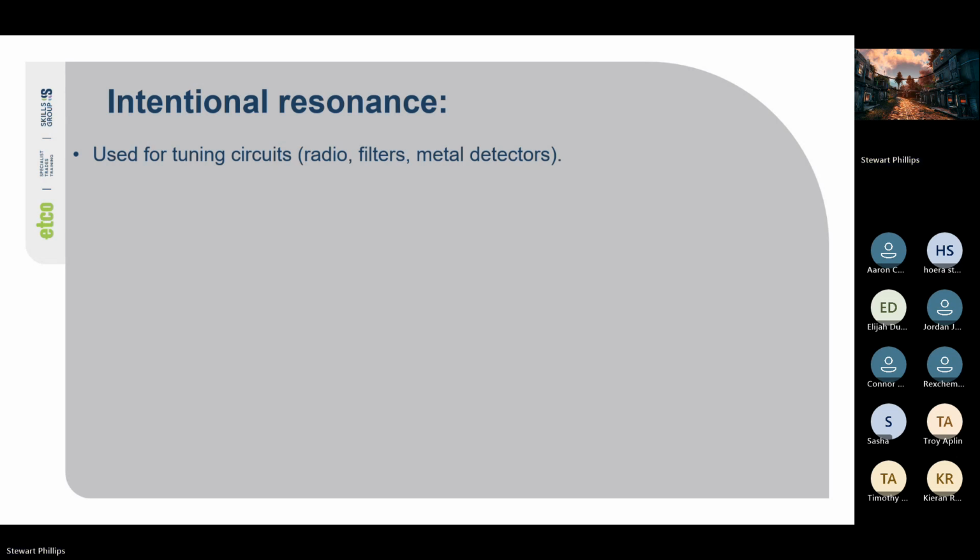I think guys who are industrial, and I mostly did commercial residential, would probably see it more, especially where they have to use power factor correcting capacitor banks. I have seen plenty of transformer fires online that possibly could have been due to resonance because the guys who work on the network, there are power factor correcting capacitors inside of the transformers, I believe, or on the outputs or inputs of the transformer.